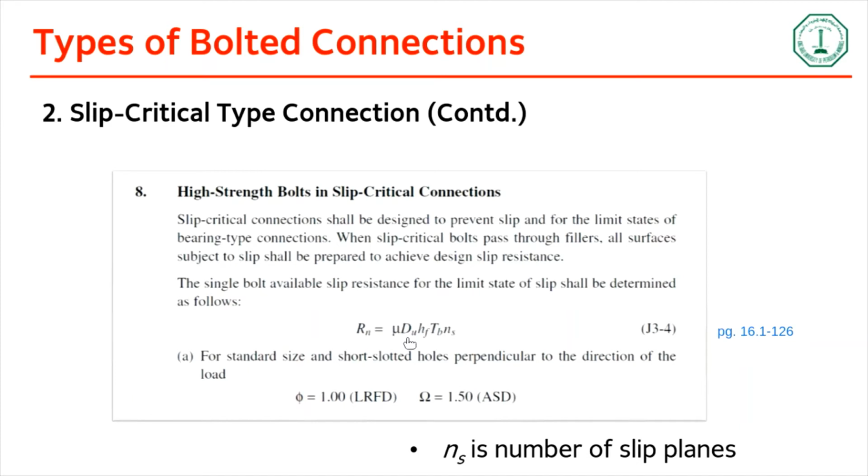So these are two surface finishes. Friction is also dependent on the texture of the surfaces. So class B would offer a higher friction. Okay, and then you have a term called capital Du, which is taken as 1.13.